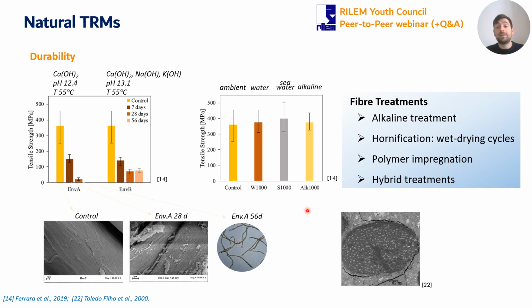So we understand that the crucial aspect is to define the right aging protocol that can better simulate the right degradation phenomenon. Otherwise, we risk not assessing the exact degradation properties of the material. Also, another aspect is the interaction between the fibers and the matrix. Here we can see, for instance, an image from the literature in which the wet-drying process has created some breakage in the interface between the paste, cement paste in this case, and the fiber.